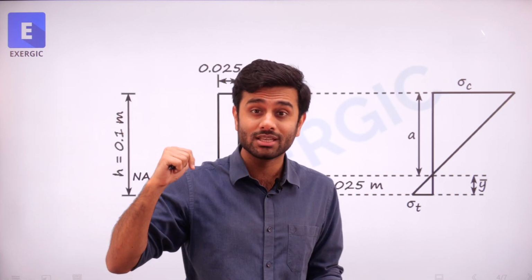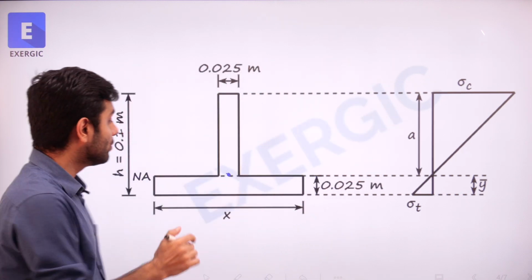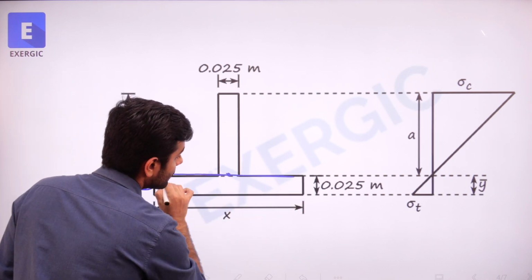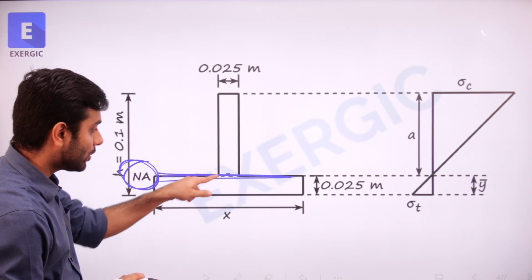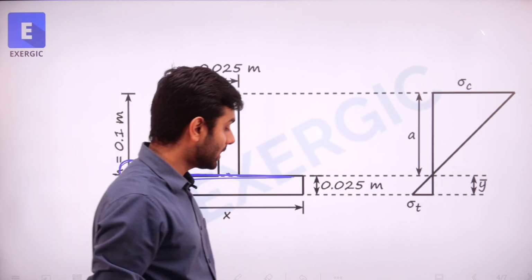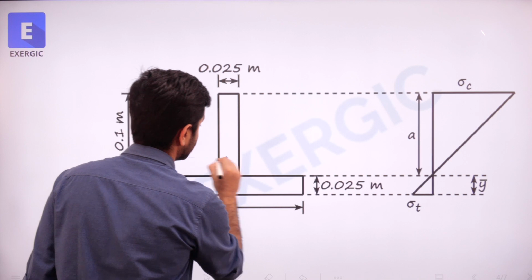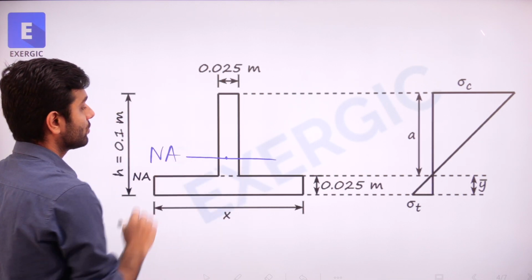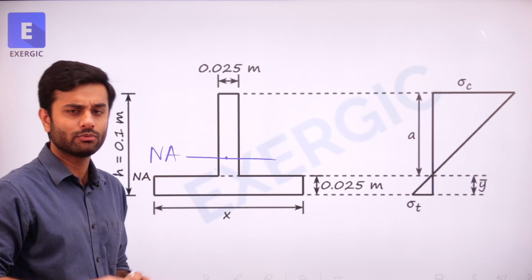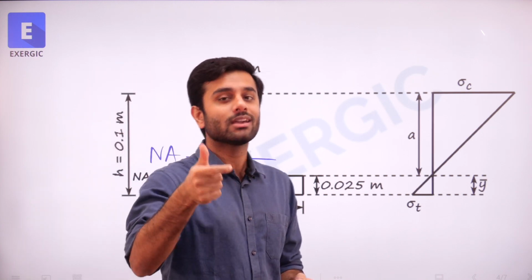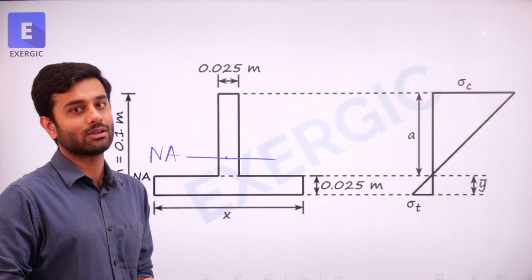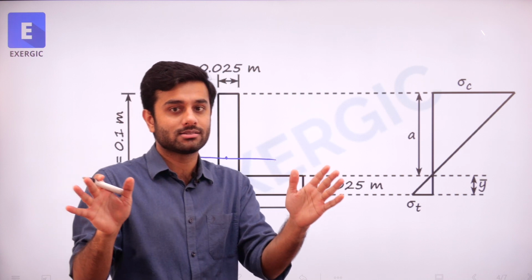This is something we are doing because neutral axis value, the position was passing from this point. If neutral axis maybe was passing from some other point, let's say it was passing from this point, then we will have to do the calculation about that point. We would get the answer. It would get slightly complicated, one step additional calculation. Right now they are simple rectangles, right?